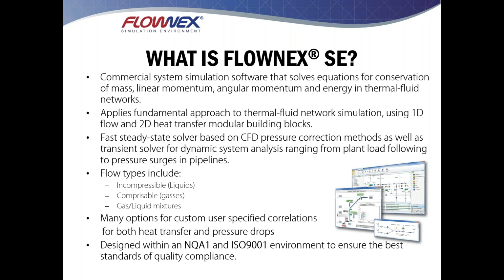We have many different fluid types inside of the software. Obvious fluids are incompressible and compressible fluids. For all our secondary flow system modeling components, we have full compressible theory applied, so no incompressible assumptions in those components. We also have a lot of other fluids available. These can be mixtures of gases and liquids, perhaps oil and air in a lubrication system, or a two-phase fluid like water where you have condensation and evaporation.